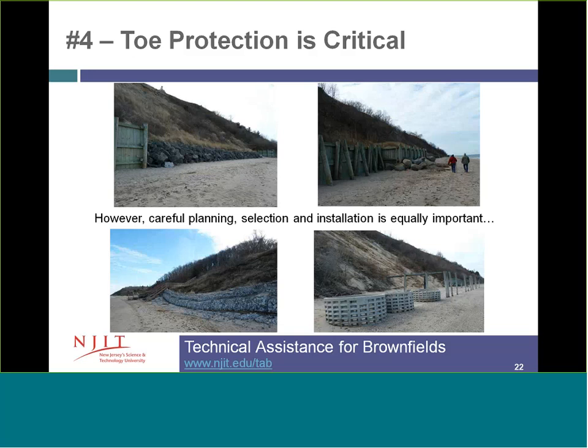And again, one of the last parameters that I find very critical, and typically the Achilles heel for many designers, is they forget to protect the toe. Toe protection is absolutely essential. If the toe isn't protected from battering both on a low-level routine basis or during storm surges, the shoreline restoration is bound to fail.